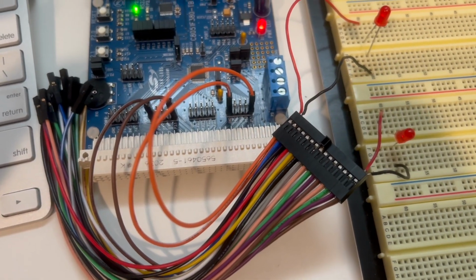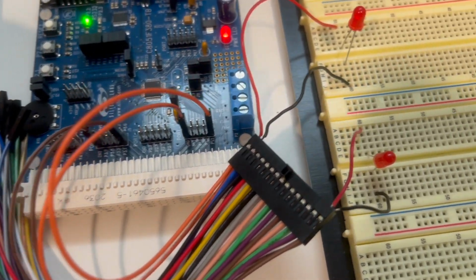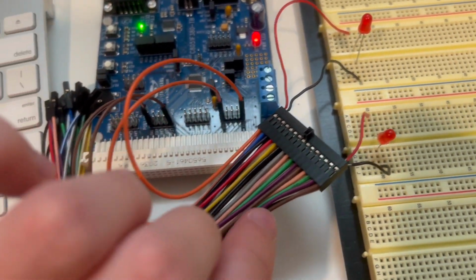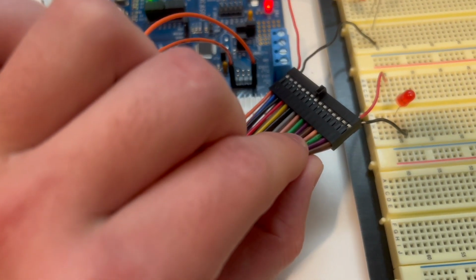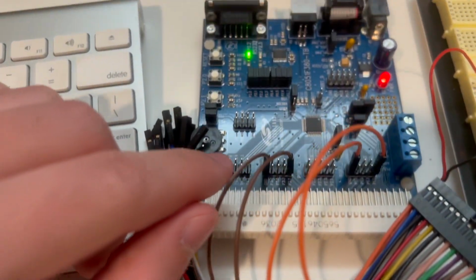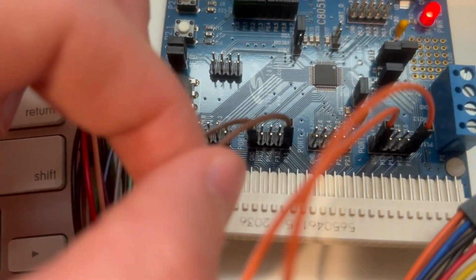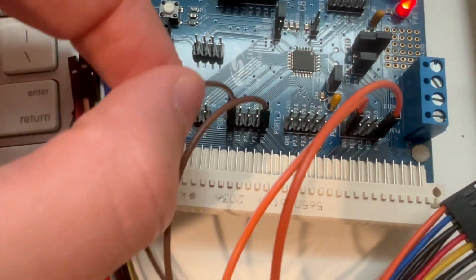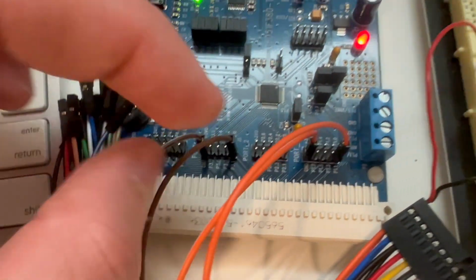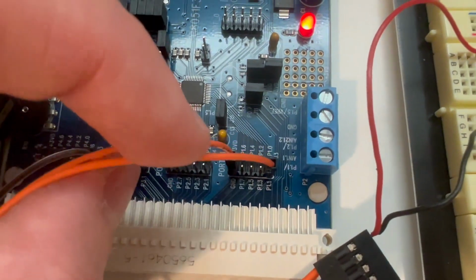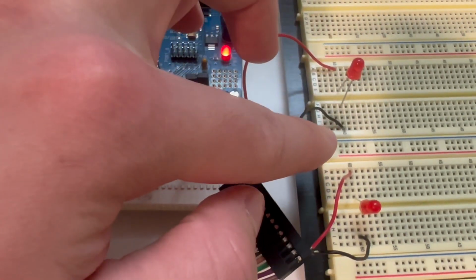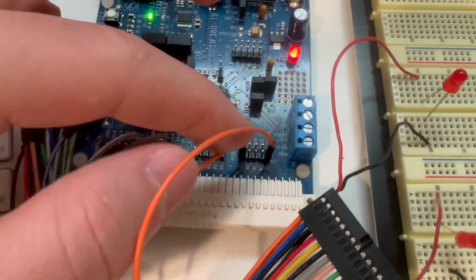Here's the construction of this circuit. The LED has a positive and negative coming off of it, and this connects to positive and ground wires that go to the microcontroller. This is the input. It shows P3.1 and the ground wire for the LED, and the same for port 1. There's a positive going out to the LED, and then there's a ground wire coming back to the ground of the microcontroller.